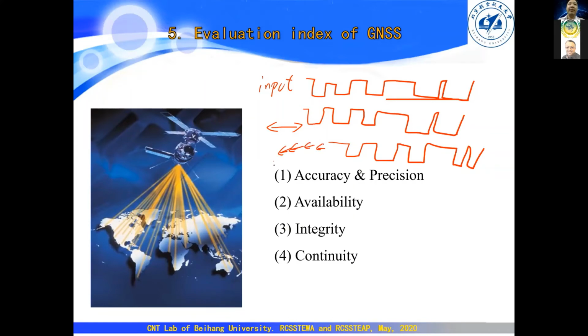So this step is 0.5 chip. So totally, we are now guessing the chip of the PRN code. We are moving to let the two chips match each other. So there are 2046 possibilities of the position. Okay, so this 2000 means not to get the chip, but to get the position of each chip. Is that clear? Yeah.